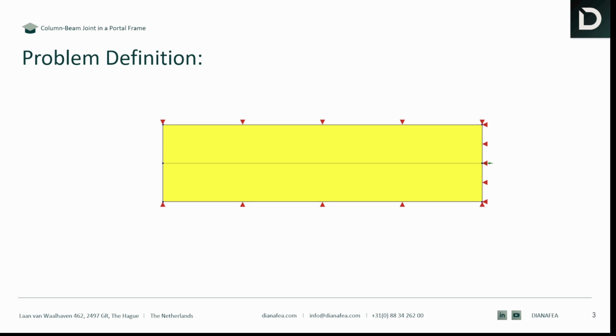In this tutorial, I want to demonstrate different bond slip models that we have in Diana. For this purpose, I will use the plane stress rebar pull-out test example. Since in this tutorial we want to focus on the interface behavior, I want to go through only the steps related to defining and assigning the bond slip properties.